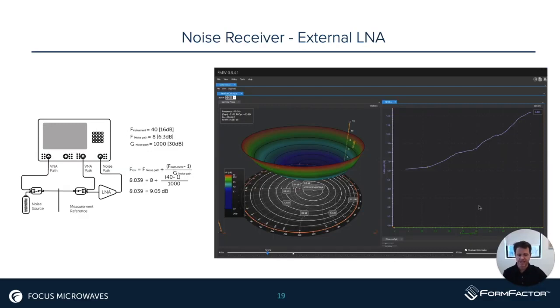So here's a quick example. I copied the same image with the same equation, but here what we're doing is an example receiver cal, and we're going to do the same thing. We're going to sweep the frequency, and as we sweep the frequency, we're going to see this noise figure kind of jumping around. We're doing, let's say, 0.5 gigahertz steps or 1 gigahertz steps, and it's basically turning around 50 ohms. So it's not as smooth as on a transistor where we're actually at gamma opt when we're high on the Smith chart. We're just kind of turning around 50 ohms, so it seems like it's moving a bit, but you can see that the values are still relatively low. Even at 50 gigahertz, we're in the range of 12 dB.